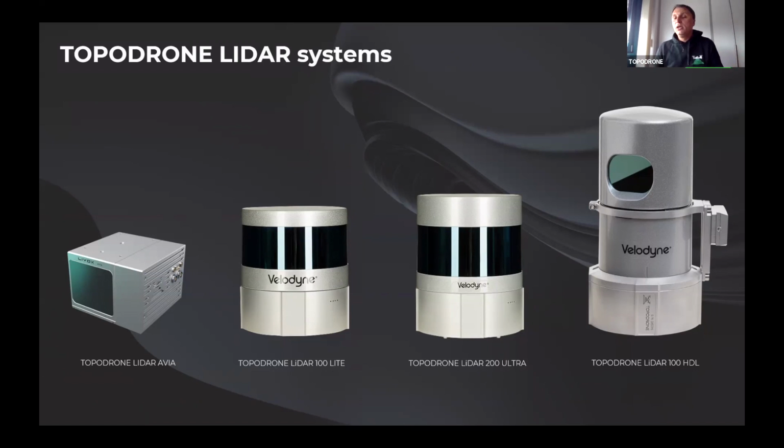You know that the DJI L1 LiDAR should be calibrated every 100 seconds. It means if you fly at 5 meters per second, the drone will stop and start to make a special calibration movement during the flight just to calibrate the IMU, because inside the L1 LiDAR we have a less precise IMU.